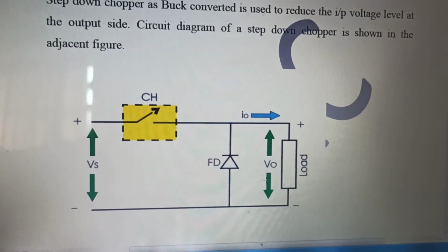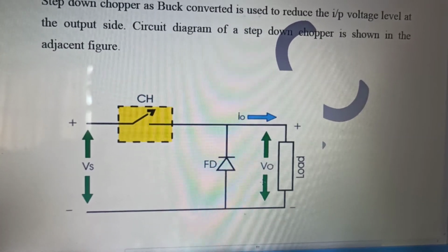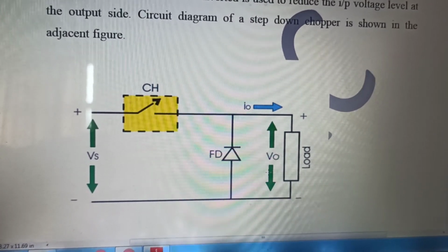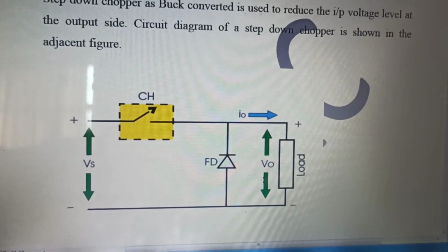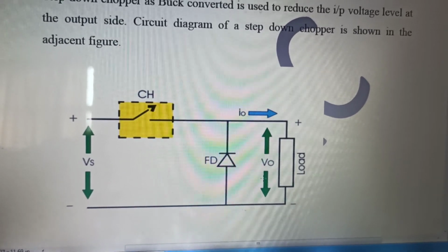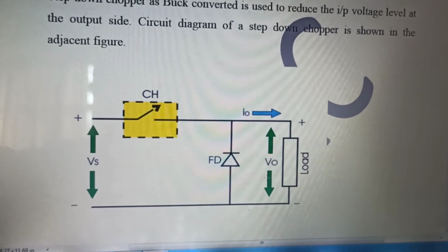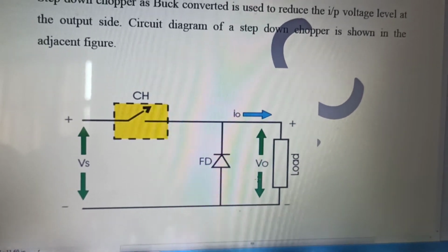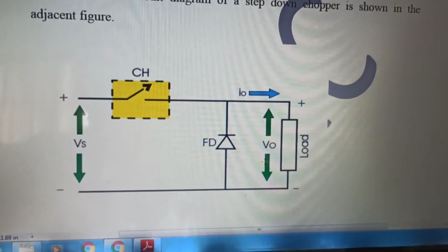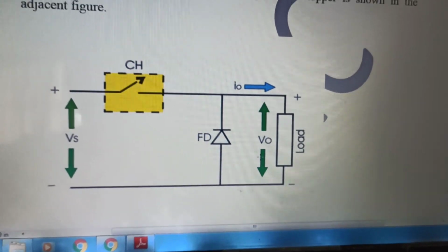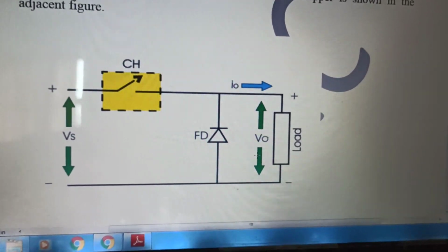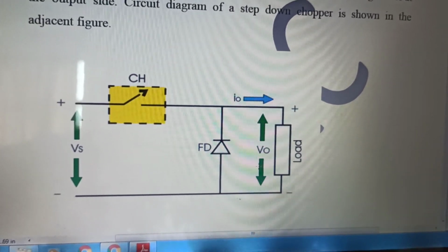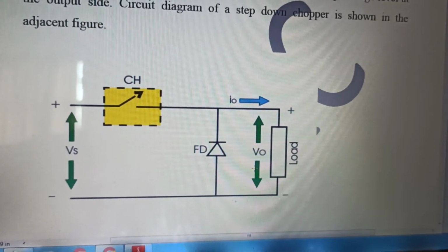Because we all know that the current is periodic, so the volt second balance will hold for that inductor. The voltage across inductor should follow the volt second balance, because the current is periodic in nature. I think that till this point I am quite clear.